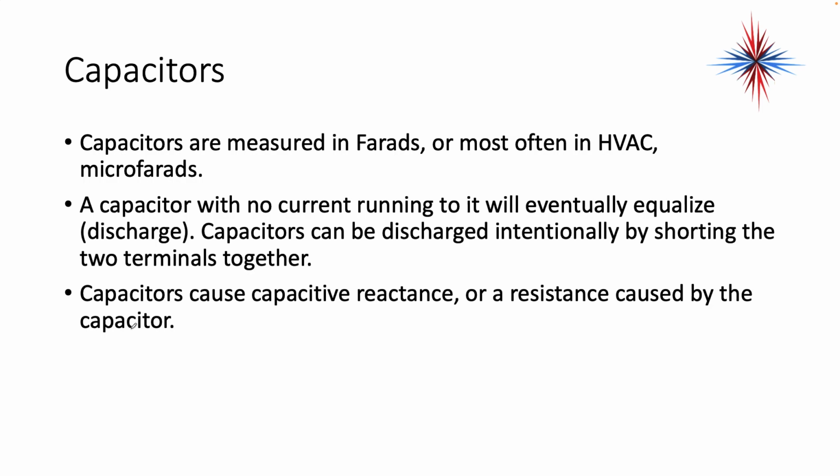Capacitors are measured in farads, or most often in HVAC, microfarads. A capacitor with no current running to it will eventually equalize or discharge. Capacitors can be discharged intentionally by shorting the two terminals together. Capacitors cause capacitive reactance, or resistance that is caused by the capacitor.